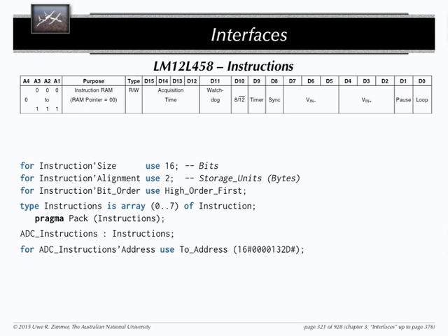So there are a number of other things. You will actually see that the syntax which you will be using will be a little bit different, but that's the basic idea. You have to tell the overall size of that record as well, number of bits which is supposed to be, the instruction alignment. This doesn't go naturally. You have to actually tell it that this has to be aligned to a certain border. And many of the devices will in fact produce a bus error, will crash your system if you address them in the wrong alignment.